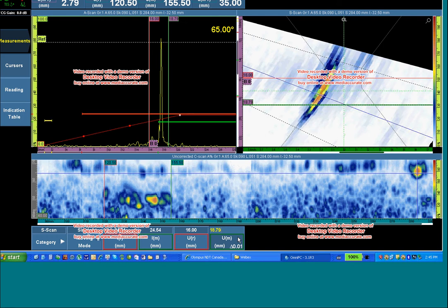Based on your weld bevel, based on your destructive testing and your procedure, somewhere in about a 3 to 6 dB drop, or in a rapid drop visualization of the flaw, you can arrive at a very tight specification of we would expect a 0.5 millimeter to 1 millimeter sizing accuracy in these type of techniques.